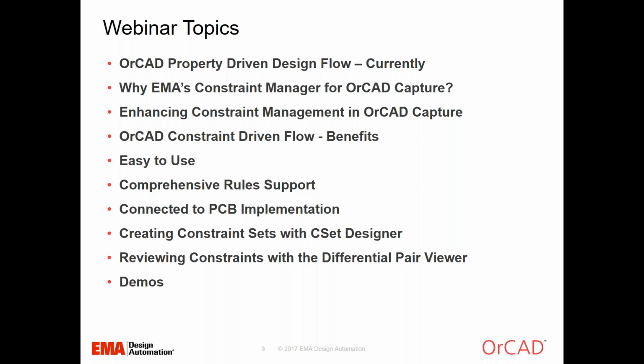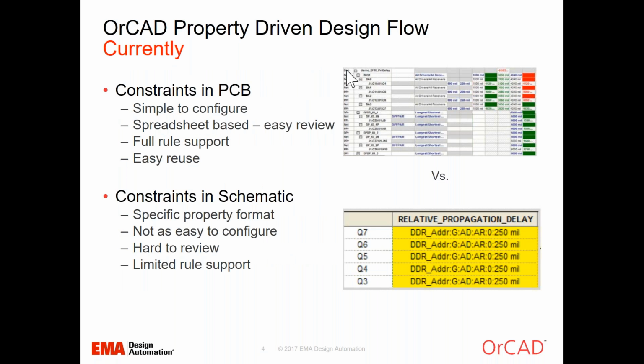I will show you how easy it is to create electrical, physical, and spacing constraints using Constraint Manager for OrCAD and pass them directly to the PCB Editor board file, where they will be used to assist with the placement and routing of the board layout. I will also cover how we can pass elements such as the board stack-up and even XNets back to the schematic to be used during constraint assignment.